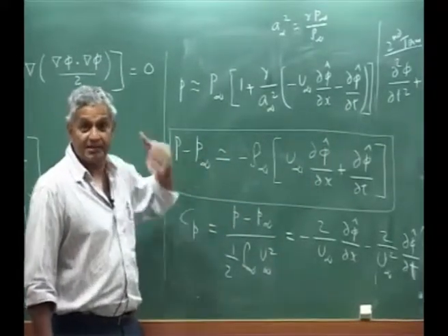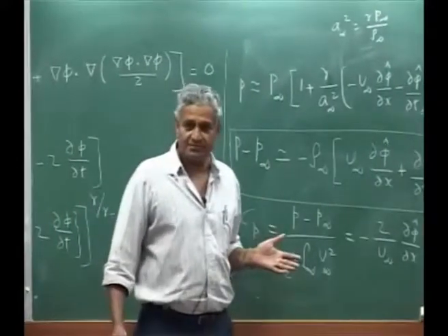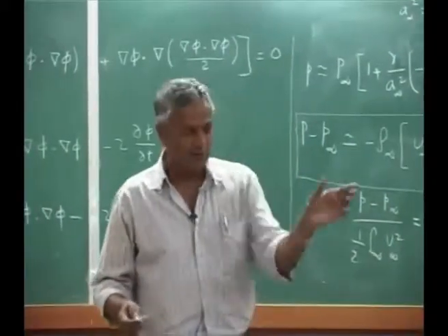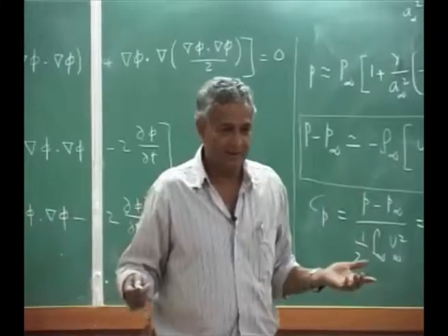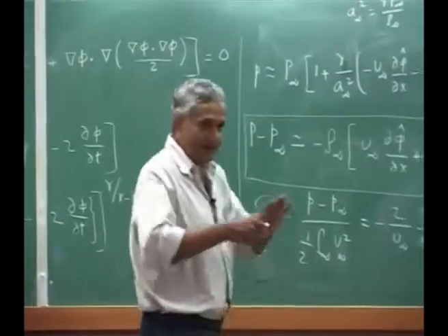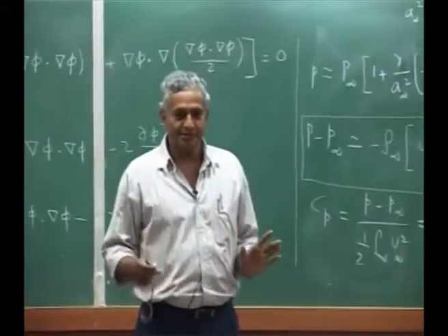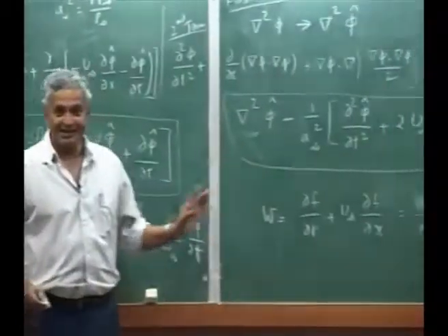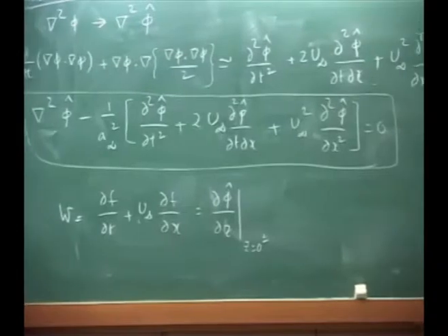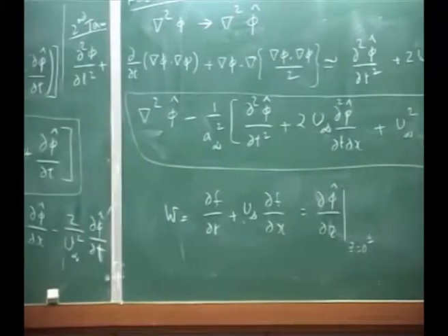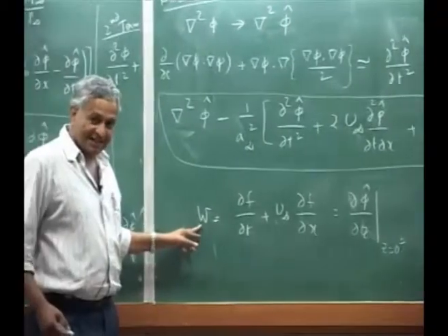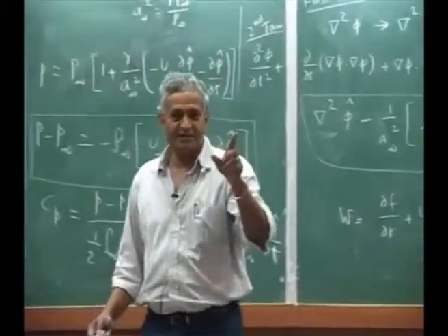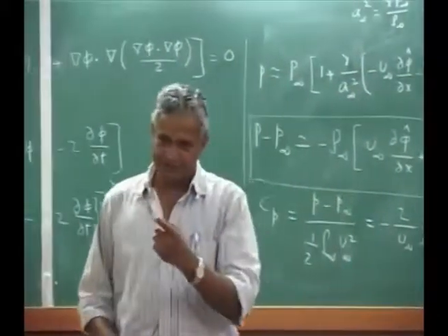Now you get pressure on the top surface, pressure on the bottom surface, and then you subtract that and you will get your lift. And you integrate over the chord of the airfoil. So finally, our entire unsteady aerodynamic equation is reduced to solving this. Only thing is, thickness we still have not brought in, because we say this W is the flow velocity on the surface, but that F we have differentiated between a top surface and a bottom surface.